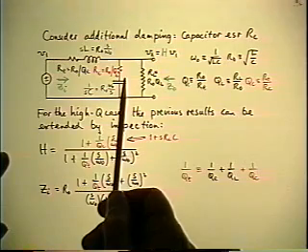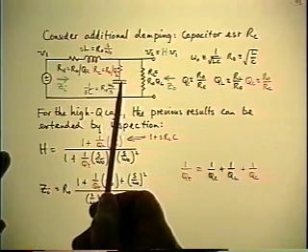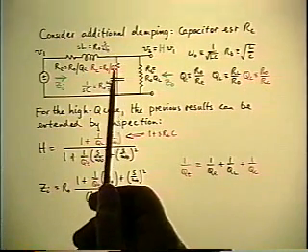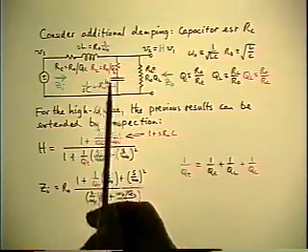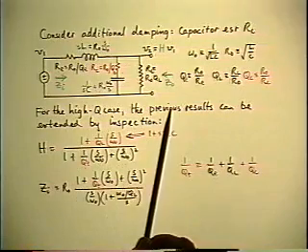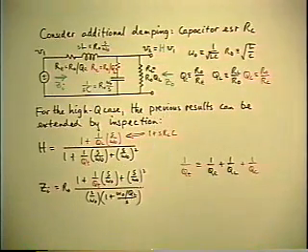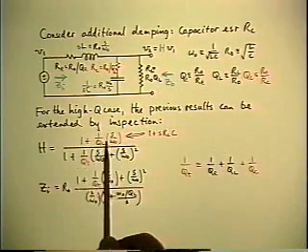Yes, it does. Because at a high enough frequency, the capacitive reactance drops below the RC, and the capacitance drops out, and you're left with the RC. That's a significant difference from the case where RC is zero. In fact, what happens is the LC filter becomes an LR filter, which is a single pole function. Therefore, the final infinite frequency asymptote, instead of being a double slope, has to come back to being a single slope, which means there must be a concave upwards corner, so there must be a normal zero. So write it in. There's the normal zero.